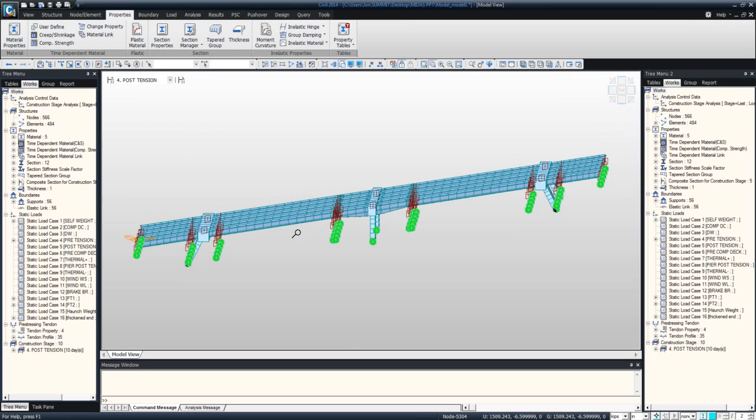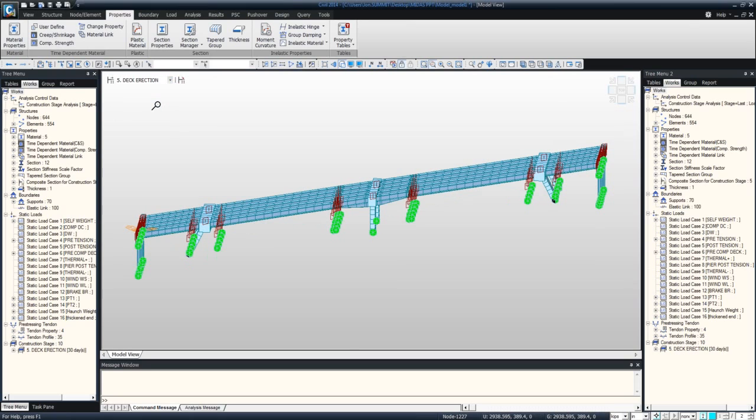The post-tension stage, we're still on the towers, although we've removed the formwork. So we no longer have formwork at the bent caps, but we do still have the towers. And we've left the towers in place for the deck erection. This is a design decision. You can limit the long-term deflection somewhat by leaving them in place while the deck is poured and cured.